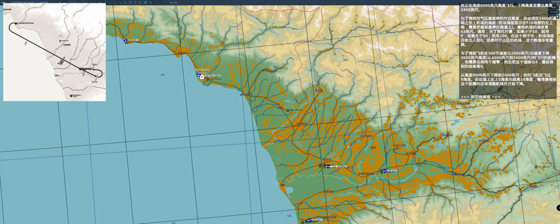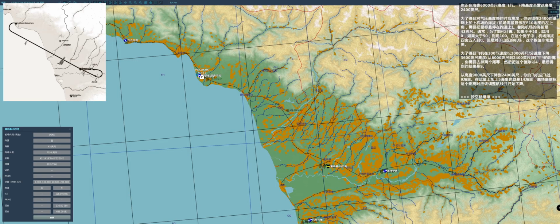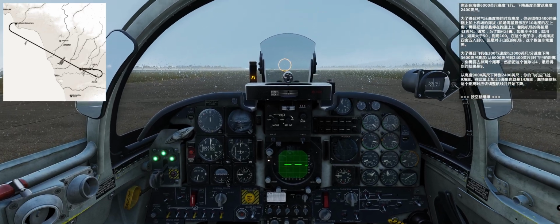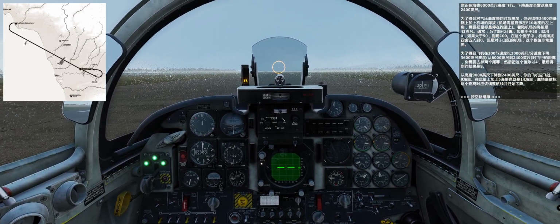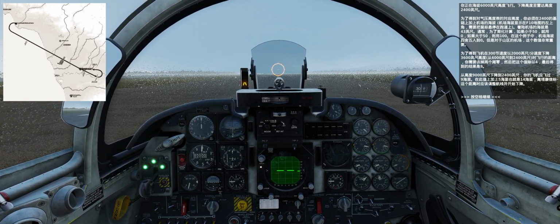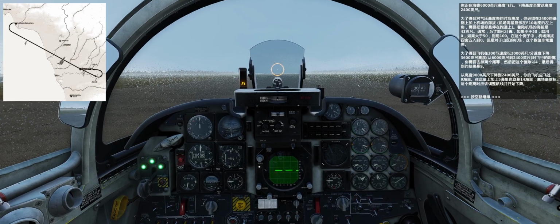Normally, to simplify calculations, the elevation is rounded to 0 if it is less than 50, or to 100 if it is bigger than 50. In this case, the airfield elevation will be rounded to 0 and not taken into account. However, for mountain airfields, these values can be substantial and play an important role.